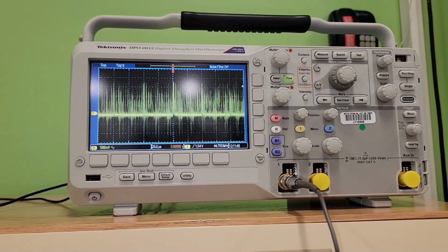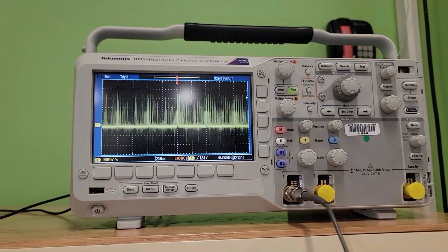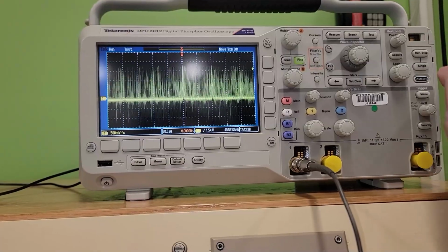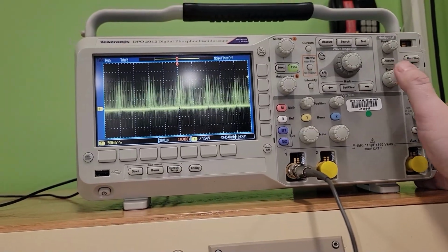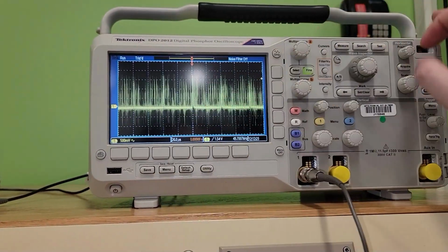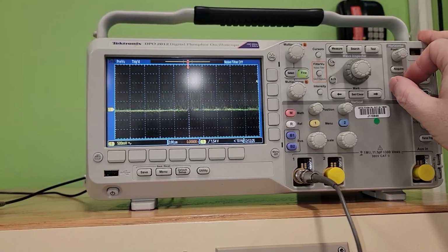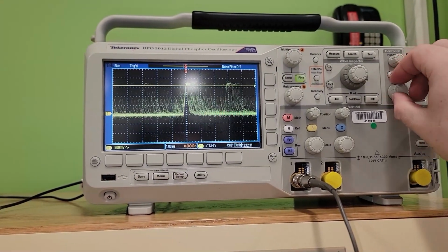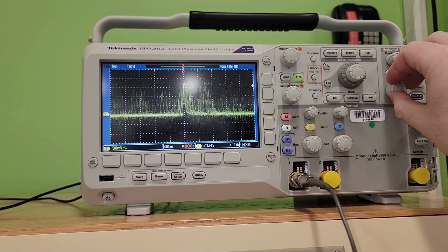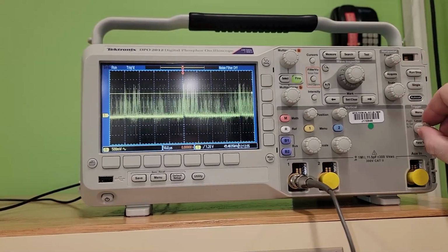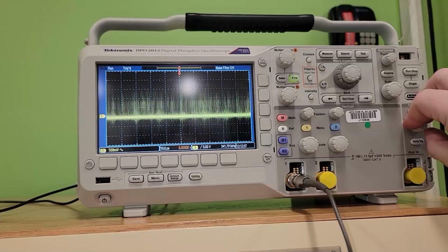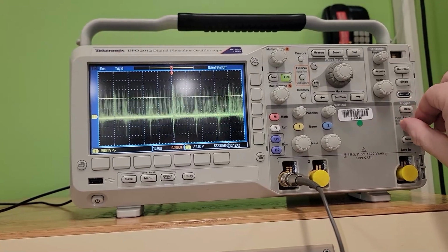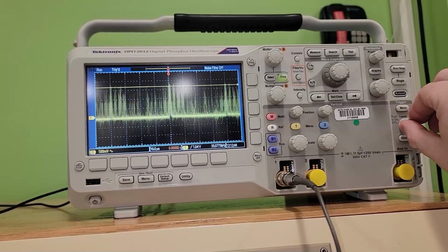Let's look at the green. I'll take that back. The next one is blue. That's on pins 7 through 9. You choose any one you want, and again, you can see the highest peak there. We'll see that again here with our sync signal. Hopefully this will make sense to you. Expand it out. Yeah, this is all my blue data. You can see that that information is repeating itself. We get a little lost in the weeds if we try to trigger at the baseline. So if you're triggering, trigger towards the peak of the signal.